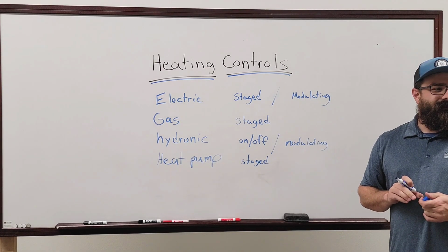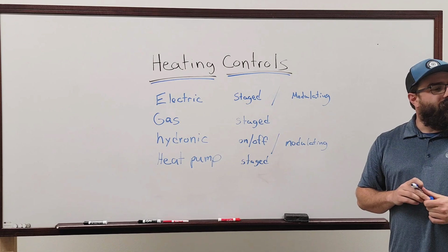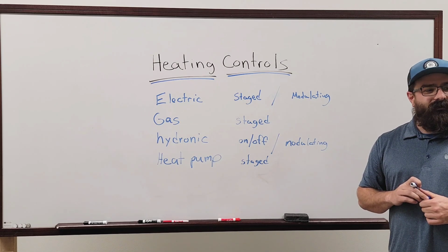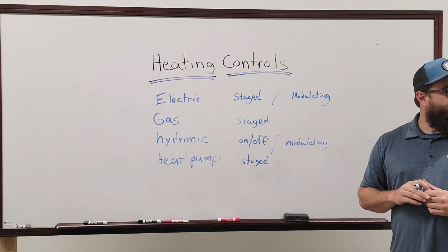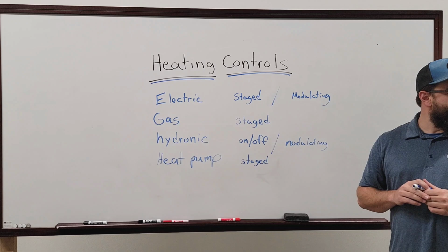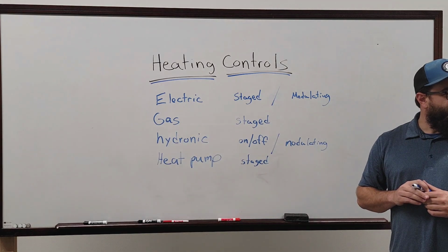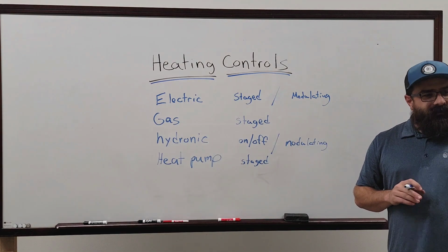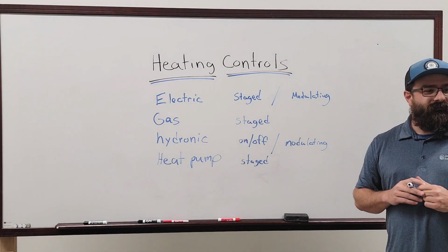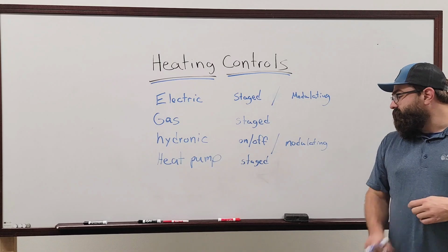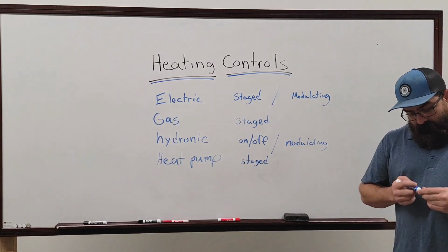So was that running heat pump or was that just reheat? Oh, you know what? That was high gas bypass. It wasn't a heat pump. That would have been reheat. That's a good point. So you're going to start really losing me when you start talking about modulated heat pumps. You're right. That was just high gas bypass. It was not a heat pump per se. Right. Okay. So we'll stick with staged then.